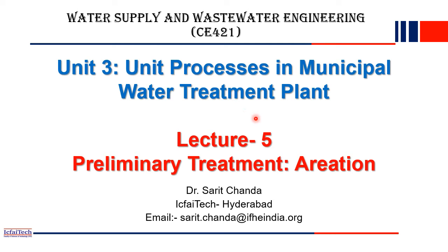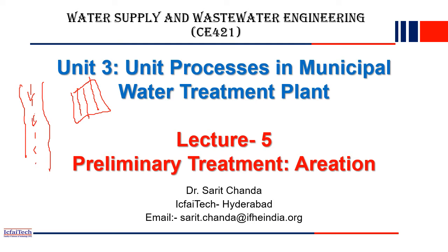Now in lecture 3 we discussed the intake structure. What is an intake structure? We have already identified the source of water, so now we have to collect the water from the source, and that collection is done through the intake structure. For example, if this is a river, our source of water, and here we have the water treatment plant with different units or chambers, water is flowing in this direction. The first step is to collect the water, so to collect it we make a structure on a river or it may be on a reservoir. That structure we call the intake structure.